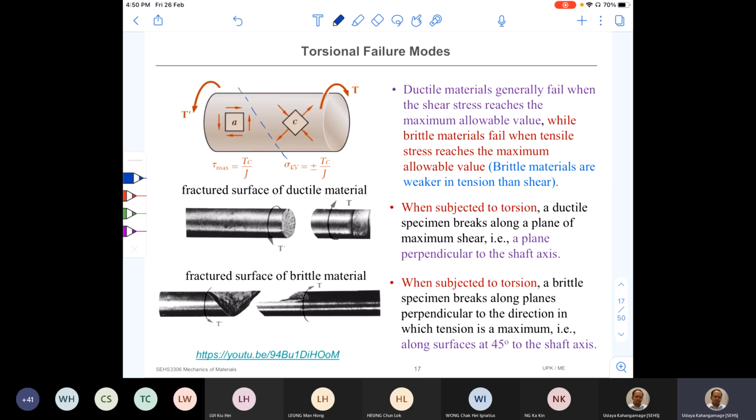This is very interesting because, depending on the properties of the material, some materials are categorized as ductile and some others as brittle. Brittle materials are hard and very weak in supporting tensile forces. They can support high shear stresses, but under tensile stresses they easily break, like glass.